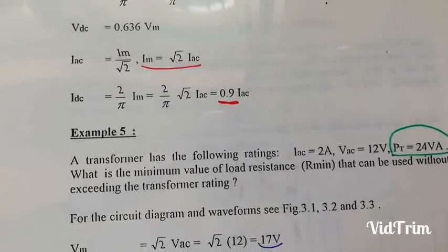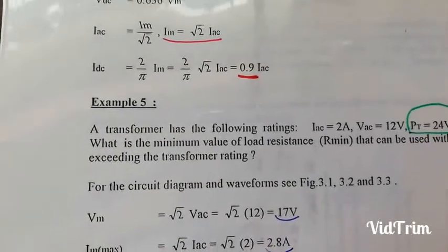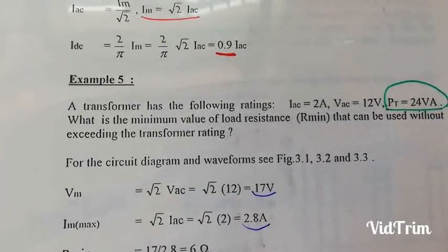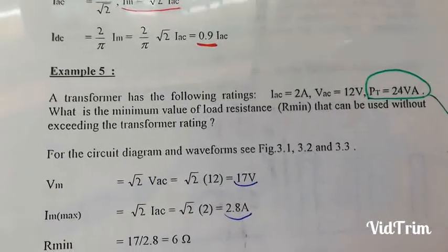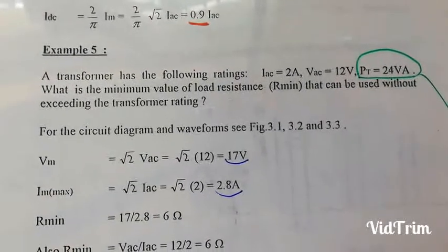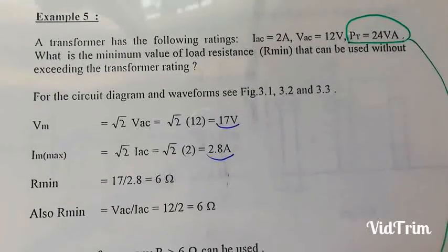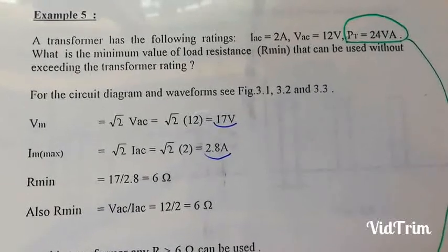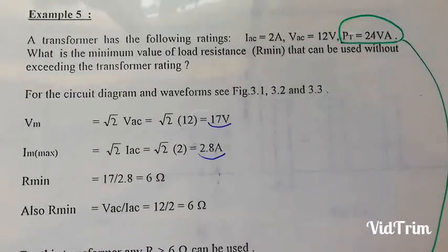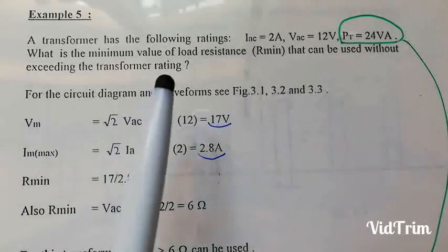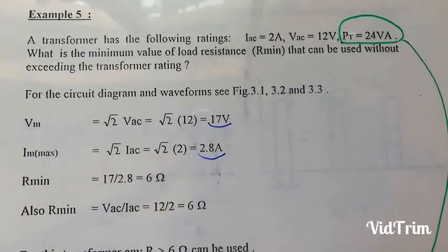Now we're going to start with this power supply without including the cap, to see how much power we're going to get out of the transformer, to see whether we are getting our money's worth out of the transformer. Okay, so we have an example here, and that example is for the full wave bridge rectifier without including the cap. And that transformer is always standard for all the configurations, and that would allow us to compare how much power we're going to get out of each type of power supply.